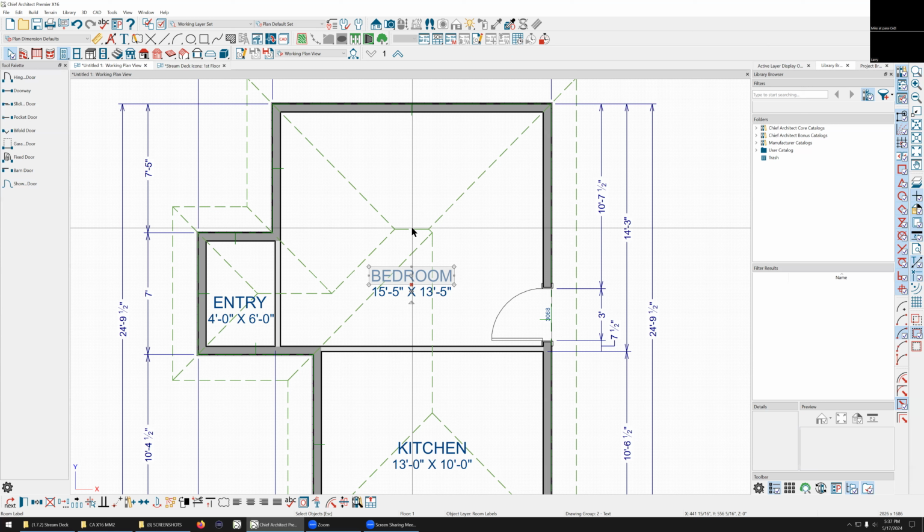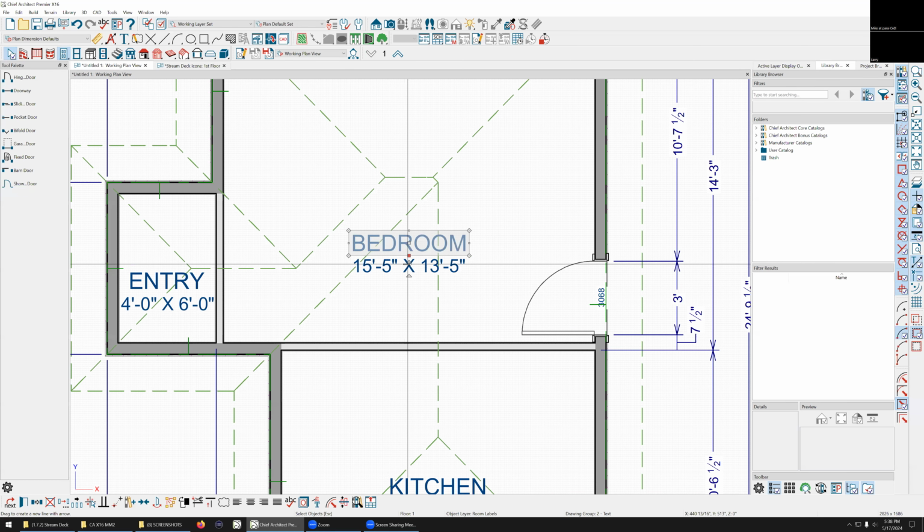The other thing that I had on my blocks, okay, when that block came in there, it automatically already had a dimension horizontally and vertically going across that room. I had it offset 16 inches from the center, so it went immediately across there, out of the way of the light fixture. And it put those two dimensions in there already, on the proper layer, proper line weight, on the dimension plan. So all of that's programmable. It doesn't take that long to write that.